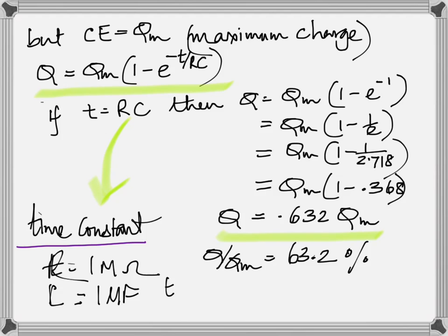Now let me ask you this. How much time will it take for it to get completely charged? How much time will any capacitor take? We're talking about an exponential charging. Do you notice that it's an exponential function? And what do you know about an exponential function? That it reaches a maximum only after infinite time. So theoretically, a capacitor never gets completely charged. Of course, practically, it'll get almost to a maximum within no time, like 1 second, or 1.5, 2.